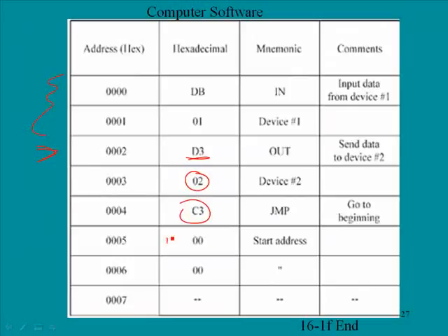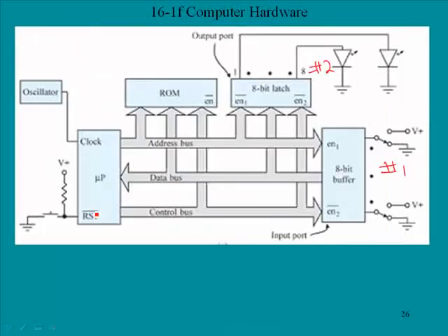The program counter is incremented and sent to the address bus with 006 on the address bus and memory read on the control bus. The memory kicks out again 00 to the data bus. The microprocessor accepts this byte and is now ready to complete the execution phase of the instruction.